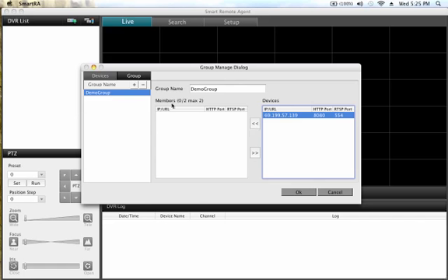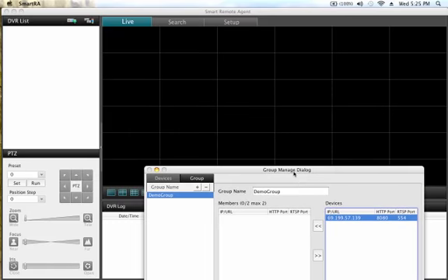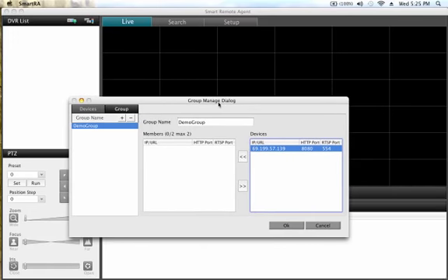You're gonna notice up here it says members 0 out of 2, maximum 2. So just remember that the remote agent software that we have here for the Mac is only capable of connecting to 2 systems simultaneously at the same time. So essentially you could have 2 16-channel DVRs, and you should have enough boxes out here to actually make all 16 show from both systems.